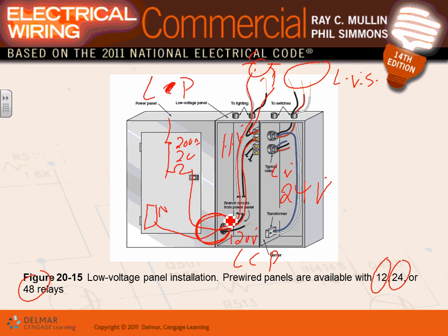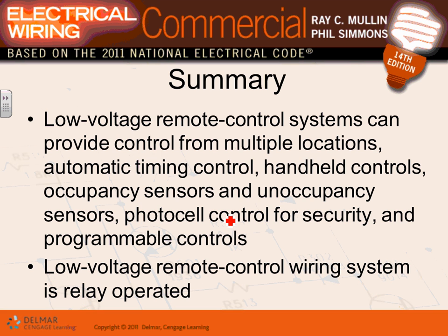We're showing relays, but you can do an interface with occupancy sensor, dimmers, timers, you name it. The same way, exactly the same way. You bring a signal from a dimmer, from the harvesting, from an occupancy sensor, a motion detector, if you want to turn lights on and off, or for security reasons, if somebody moves in the area. So that's basically what we talked about, guys.